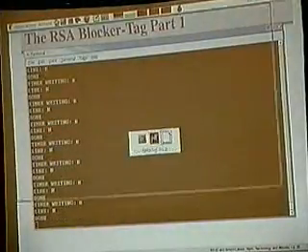So, what does one of these RFID gates look like? You see here two lights, a red and a green one. If a pallet goes through this RFID gate, these square white boxes are the readers and the antennas, and the black box at the top is an industrial PC to process the information and transmit it over an Ethernet port.